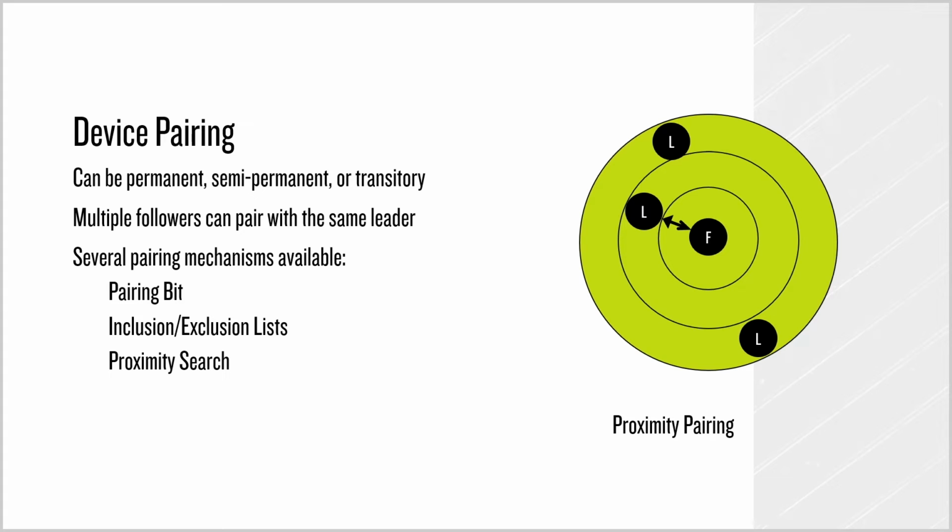A leader's channel ID is broadcast with every message. Recall that the channel ID is made up of the transmission type, device type, and device number. When a follower's channel is opened, it has a couple options for how to set its channel ID. If it knows the channel ID of the channel it is trying to connect to, it can set its channel ID to that ID and begin searching. If, on the other hand, the follower does not know the exact channel ID of the device it is trying to connect to, it can use a wildcard search. A follower can wildcard any of the channel ID fields by setting them to 0. So, if, for example, the device is trying to search for a heart rate sensor, but the device number is not known, the device type can be set to the heart rate device type, but the device number can be set to the wildcard value.